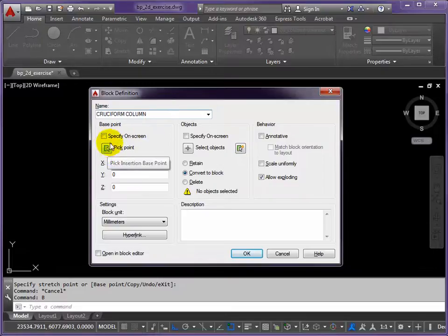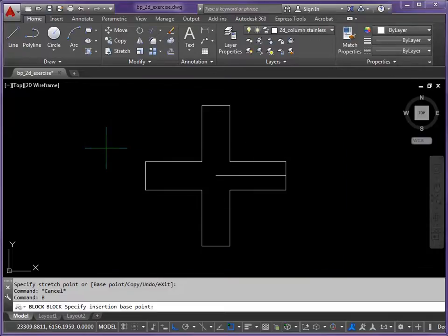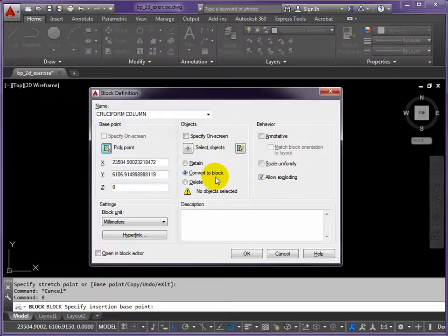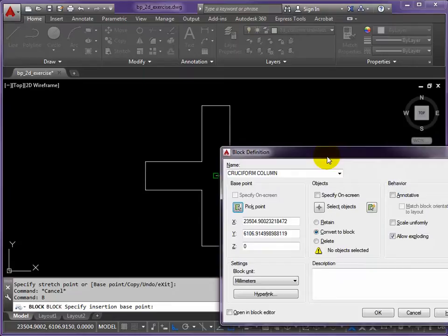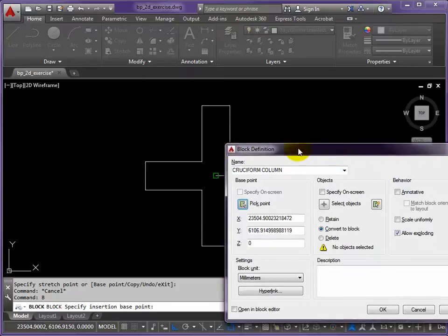Okay, I want to choose a control point, so this is also termed the pick point, and the control point will be where we started the shape, just here. Don't worry that this shows a very nasty number, it doesn't matter. It's the control point in its relative position to the rest of the shape that's important.